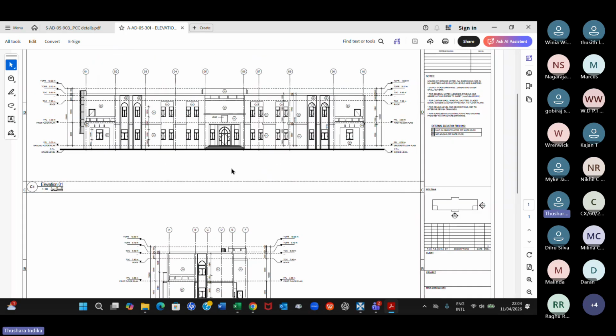So we have measured the foundation, or not all, but the majority of the elements we have already measured, including excavation. Backfilling you can do without any trouble. If you are a good QS, you know the excavation quantity, and then you deduct the concrete quantities within the excavation, and you will get the backfilling. So there's no measurement to be done.